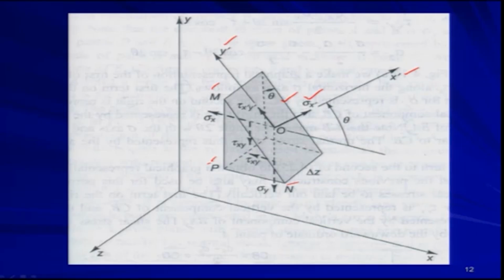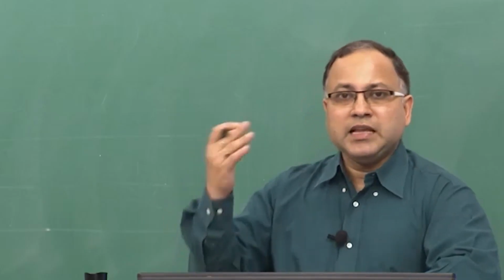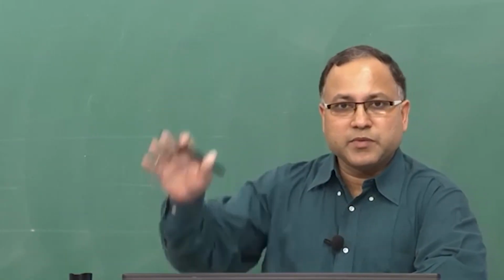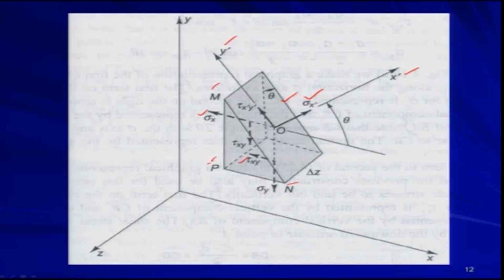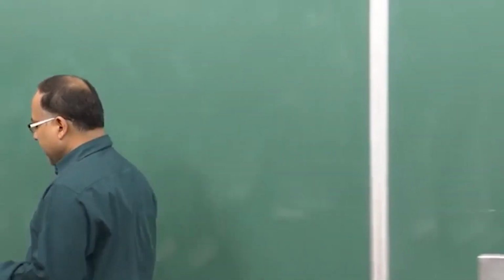Sigma x causes force in the x direction, but I can take the component of that force along the x prime direction. Similarly, tau xy acts along the y direction on one plane and along the x direction on the other, so I will take the components of that stress also.